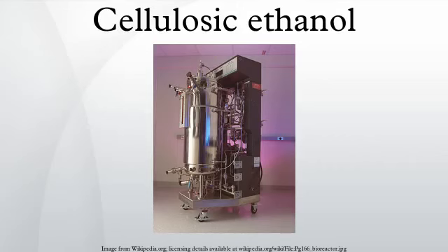The process can thus be broken into 3 steps: Gasification. Complex carbon-based molecules are broken apart to access the carbon as carbon monoxide, carbon dioxide and hydrogen. Fermentation. Convert the carbon monoxide, carbon dioxide and hydrogen into ethanol using the Clostridium ljungdahlii organism. Distillation. Ethanol is separated from water. A recent study has found another Clostridium bacterium that seems to be twice as efficient in making ethanol from carbon monoxide as the one mentioned above.